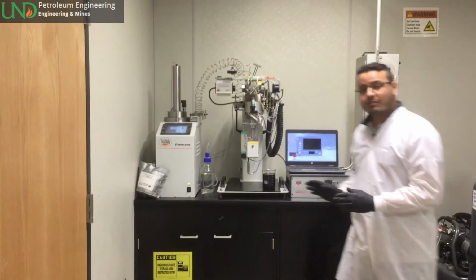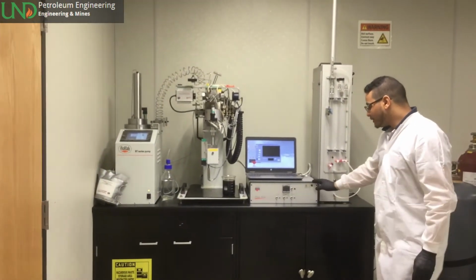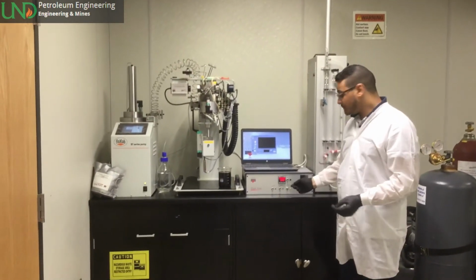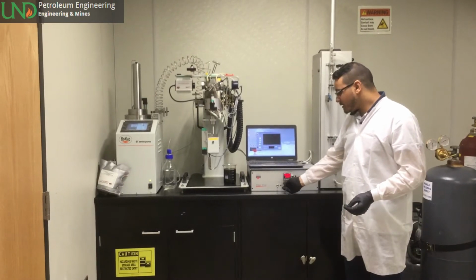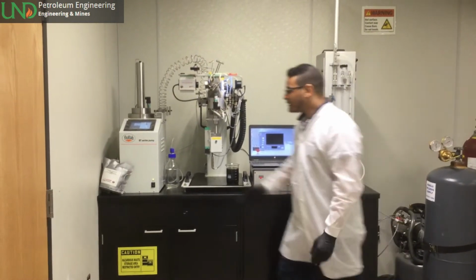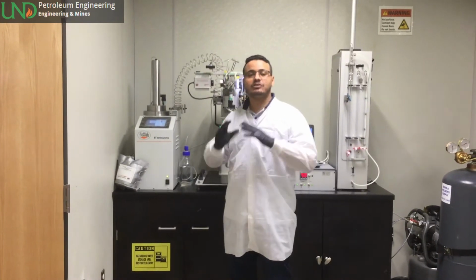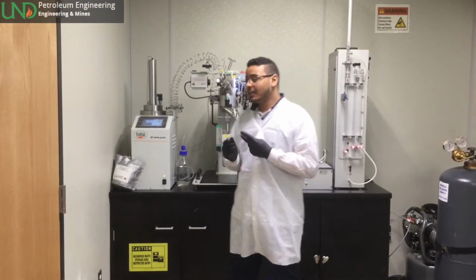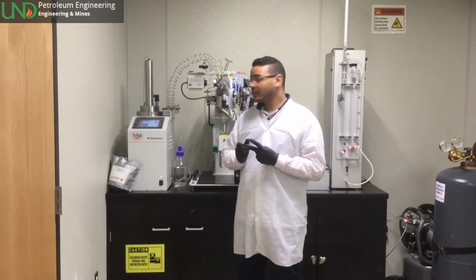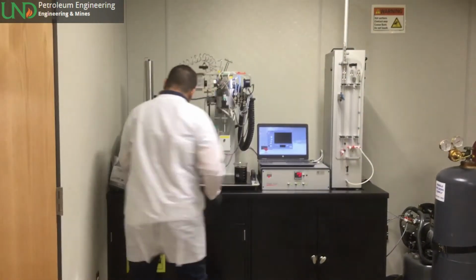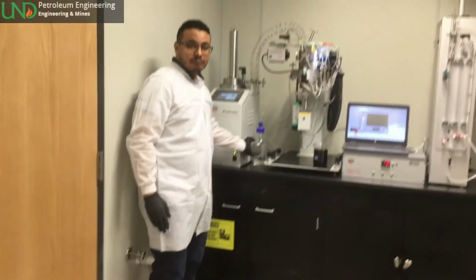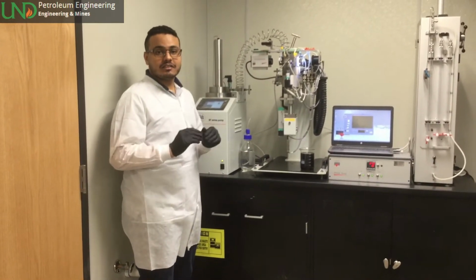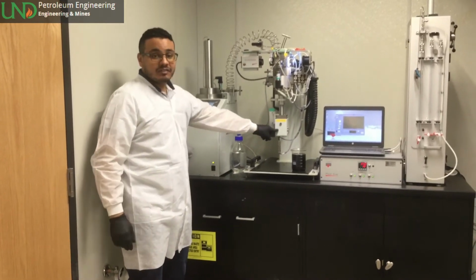The system consists of 4 main parts, starting with the control panel, where we can switch on the system power, temperature, stirrer, and the light. The second part is the pump, where we can generate up to 10,000 psi pressure using either constant flow rate or constant pressure. And we can fill the pump with tap water to displace this piston to reach the desired pressure inside the PVT cell.